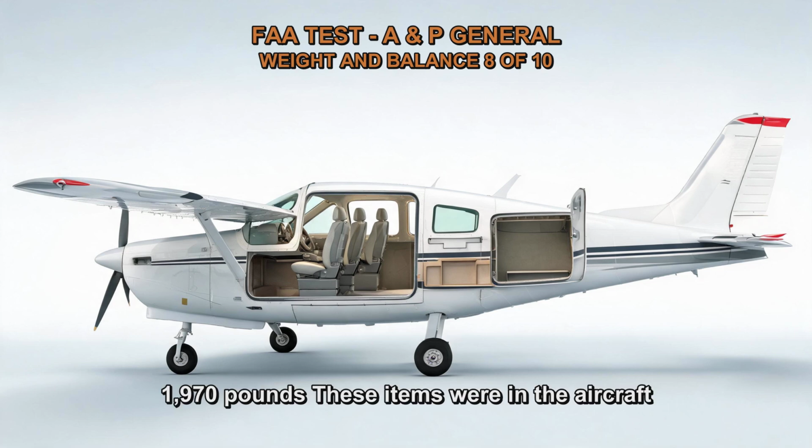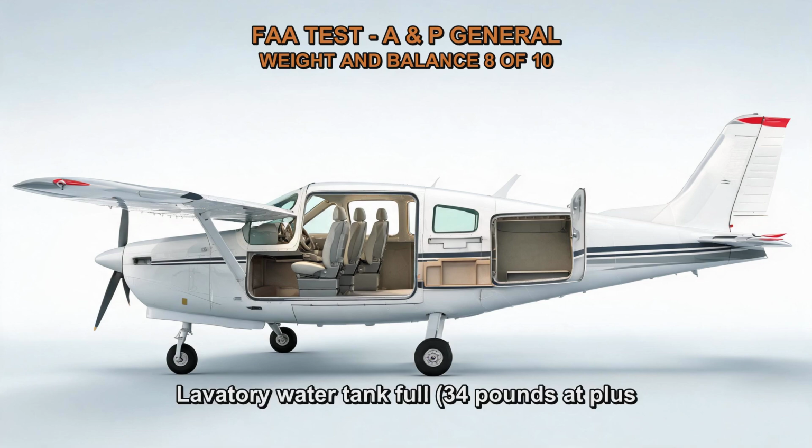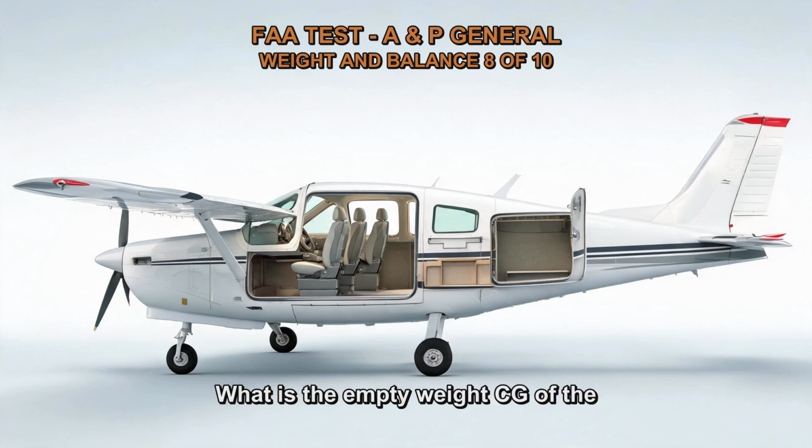These items were in the aircraft when weighed. 1. Lavatory water tank full, 34 pounds at plus 352. 2. Hydraulic fluid, 22 pounds at minus 8. 3. Removable ballast, 146 pounds at plus 380. What is the empty weight CG of the aircraft described above?